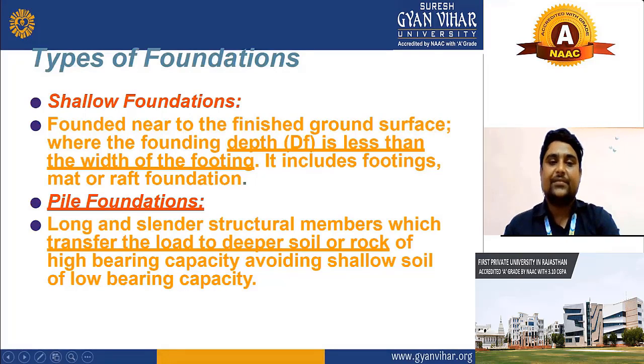Now there is the definition. Types of foundation: shallow foundation is founded near to the finished ground surface, where the founding depth, which is also denoted by Df, is less than the width of footing. It includes footing, mat, and raft foundation.